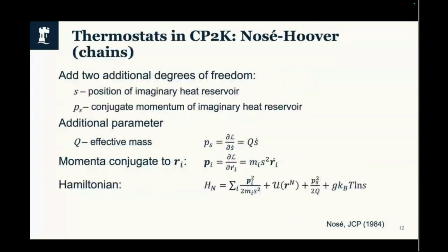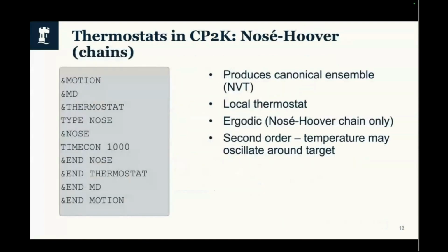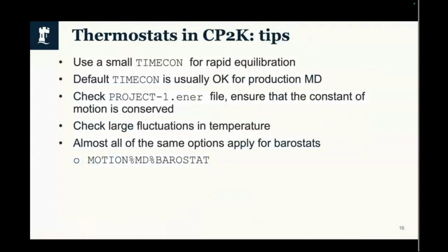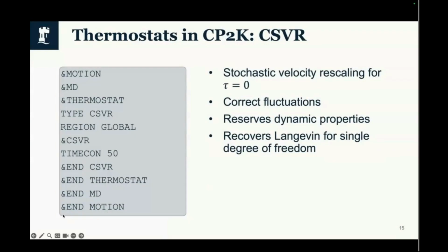So basically we have different thermostats. We can set it in the input script here, and most importantly, for example, we have to set up the time constant, tau, here, and this determines how frequently your system exchanges energy with either the thermostat or barostat.